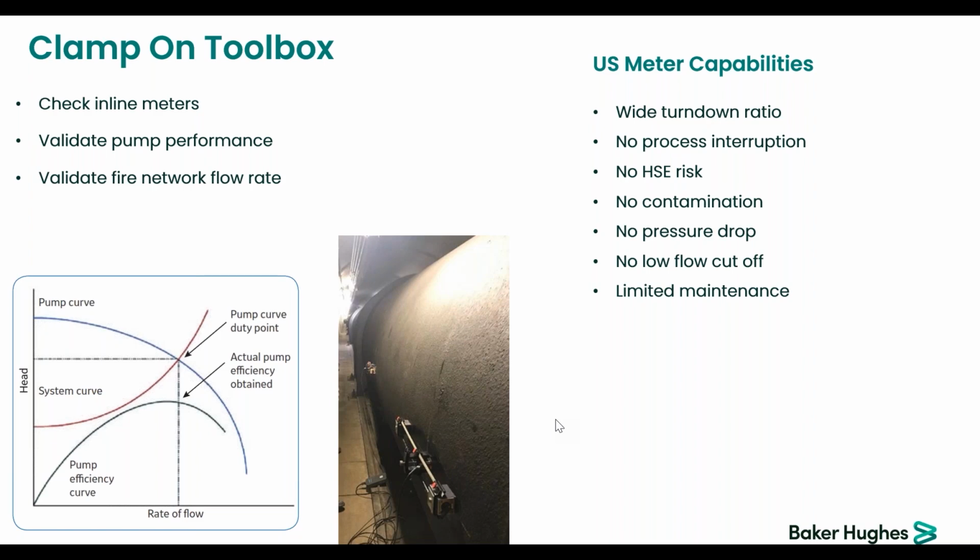The question is, on a dirty pipe, should we guess the thickness of the debris on the walls? Oh, that's a difficult one. In fact, we would recommend a thickness gauge, which comes with the portable as an optional item. So we would recommend taking the thickness not only at one point of the pipe, but at different points. You take 4 points, evenly distributed, so that you have the thickness measured on those 4 points and you get an average.